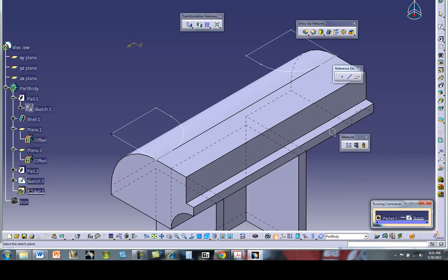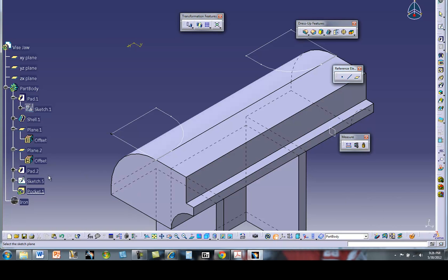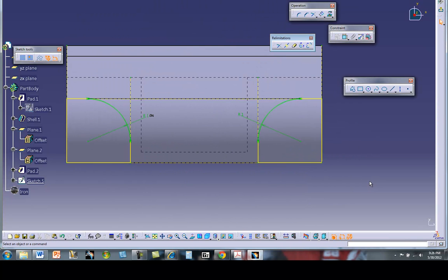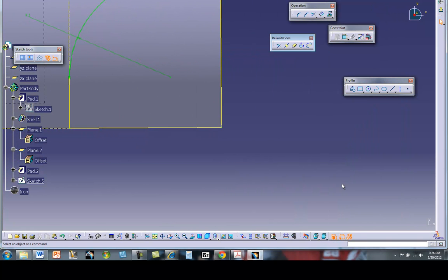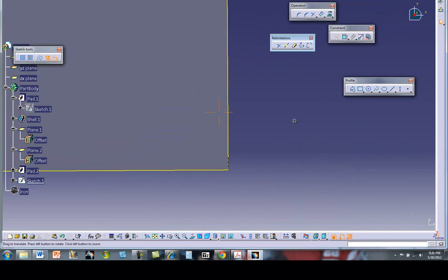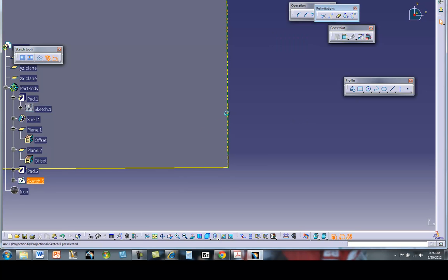Okay, let's go into the sketch of this one. Get out of here. And look at this sketch here. Let's back out. Go back into the sketch here, and if you zoom up on here, you will probably find an error. You notice I never trimmed that one. That's why it's a good idea to go around and trim things. Trim it from there to there. That should close that up if you have the command on. Trimming it from there to there closes that up.